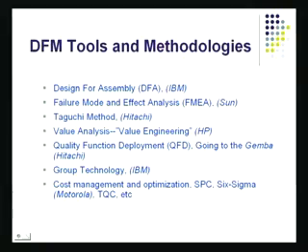Whatever the customer is looking for, I've got to capture that by capturing the voice of the customer through this QFD process. Then of course, if there are similar parts to be made, I've got to take advantage of something called group technology. If there are a lot of turning operations of different dimensions, we'll have to keep in mind that these turnings are grouped together and done at one workstation. Otherwise you'll have dissimilar processes all being thrown at the workstation, and there will be a lot of switchovers, a lot of changes, a lot of setup costs incurred additionally. This is something you'd like to minimize, and this is why you'd like to go into group technology.